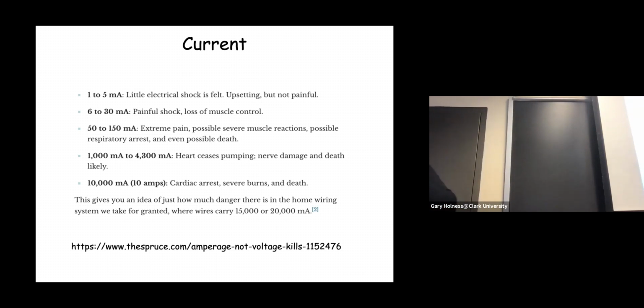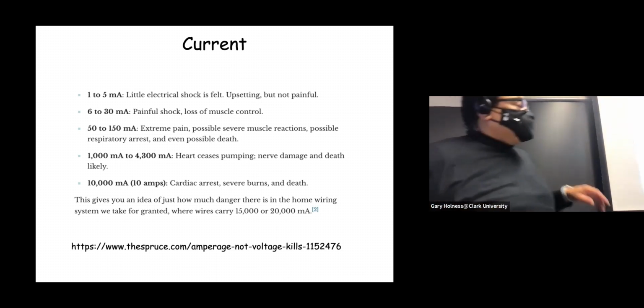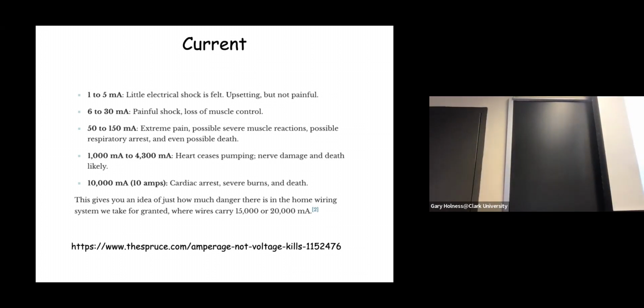Current is drawn, not pushed. And I'll explain what I mean about that subsequently. But when you have a high current line, you want to exercise caution. If you've ever dealt with a car battery, like when jumping a car, there's a specific order that you attach the leads because you don't want to make yourself the path to ground. You want to make the car the path to ground. Okay? All right. Any questions?